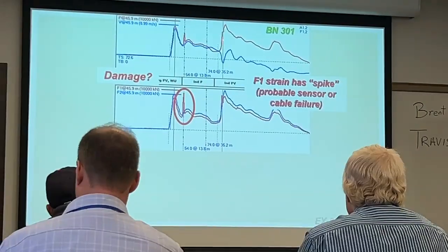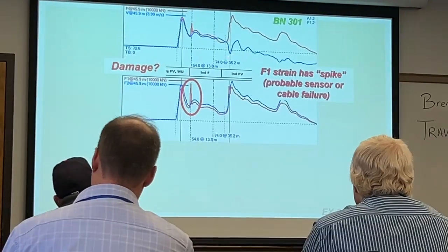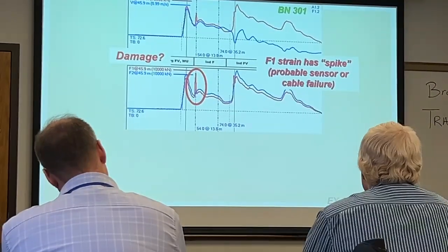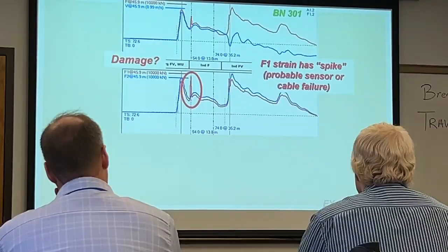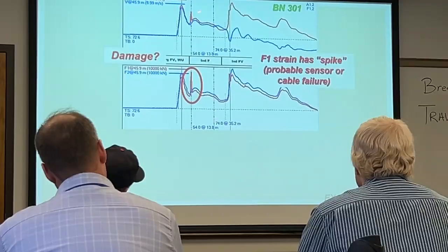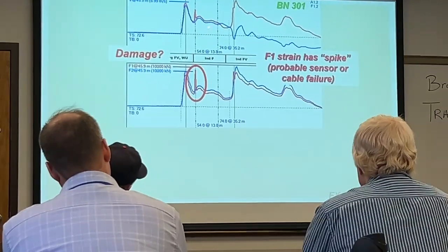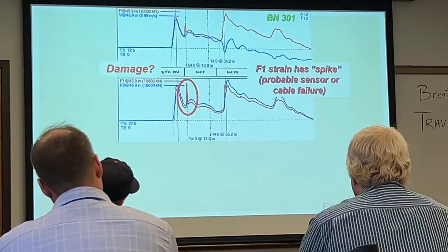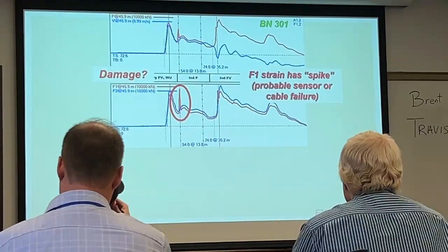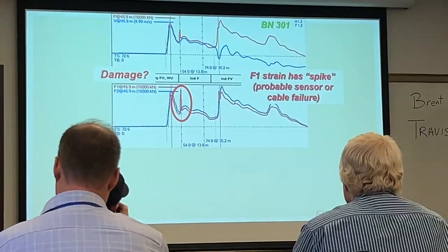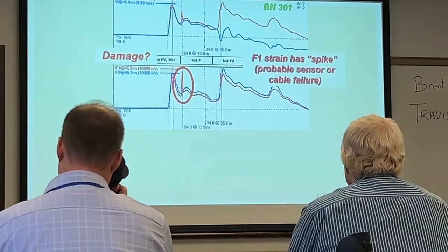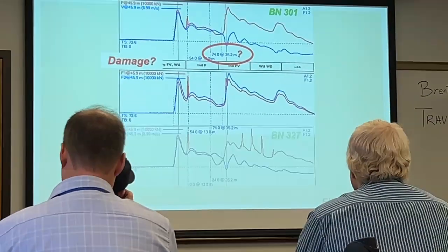When we get to 2L over C, our velocity goes to zero, and our force doubles. What does that mean? Fixed end. So we are at rock. So what's happening here? The pile was driven to rock, but we're starting to generate damage somewhere above it. Either because the rock is maybe a little sloped, or we're catching ourselves in the bottom of a boulder or something. So that one is correct.